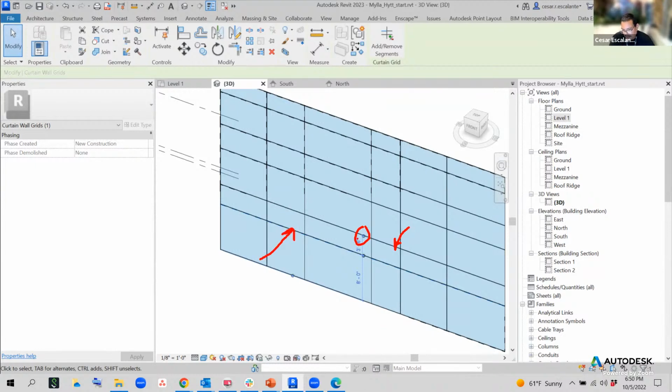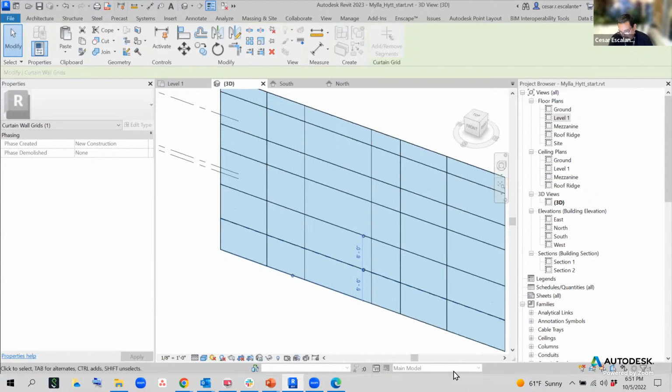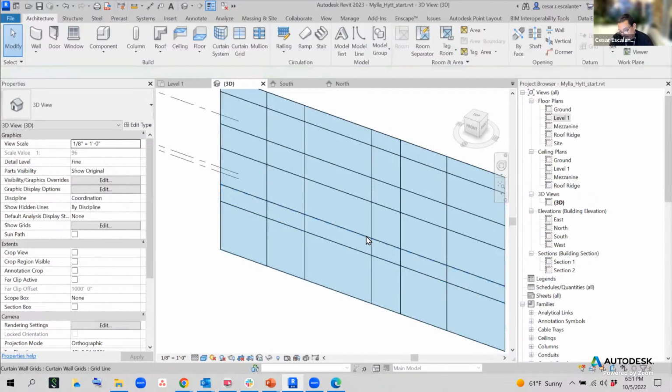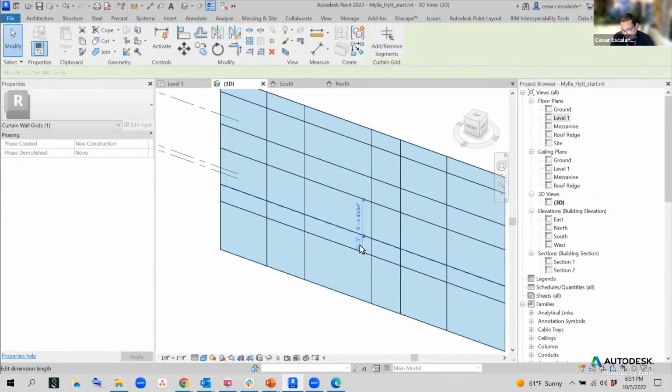So in order to move the line above, you need to select the line. So I'll select this grid, and the relative location of that grid is 6 feet. Everything you select is movable. So I'm going to return this back to 3. If you want to move the line above, select the line, and then change the relative location. And then make this 6, etc.